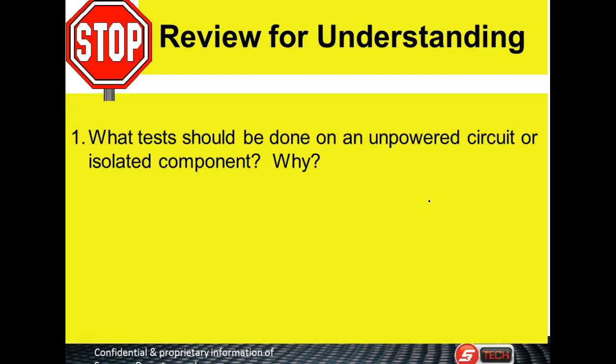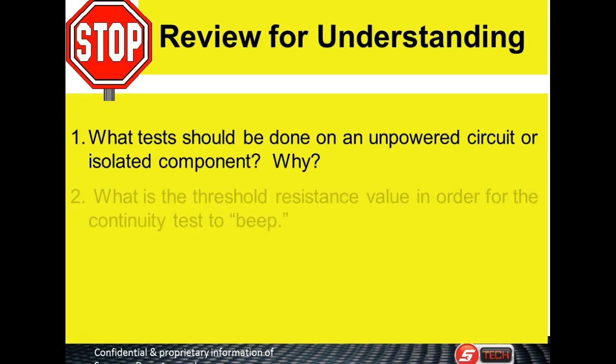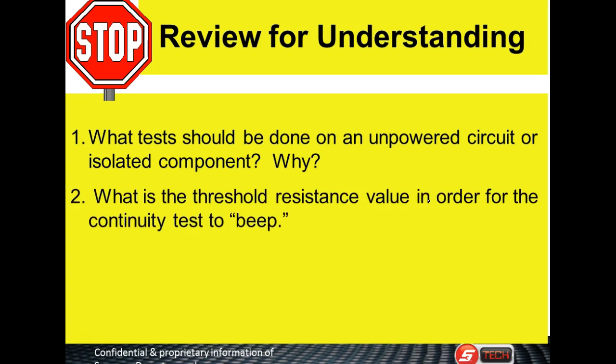So what test should be done on an unpowered circuit and isolated components? What would we measure with our meter when the circuit is unpowered? What do you think we'd be looking for? Yeah, resistance, right? And why? Because you can mess up your meter if you put it in a powered circuit. What is the threshold resistance value in order for the continuity to beep for this meter? I remember? That's 30 ohms.